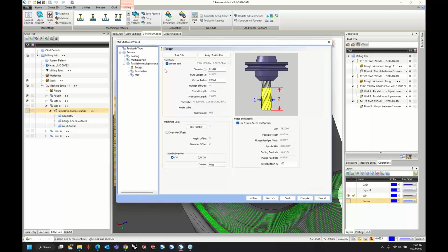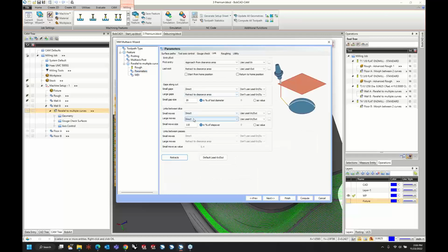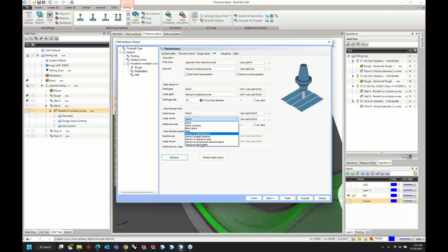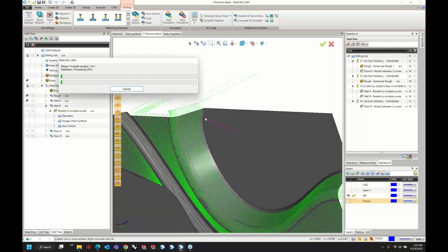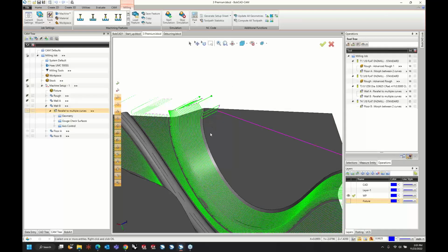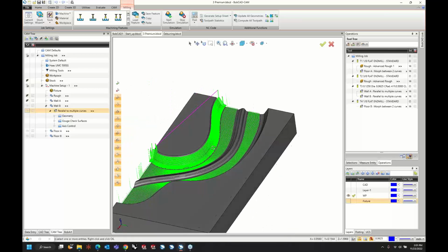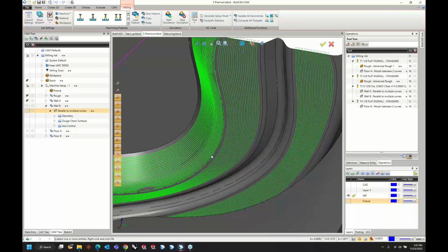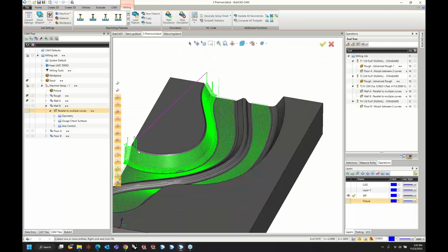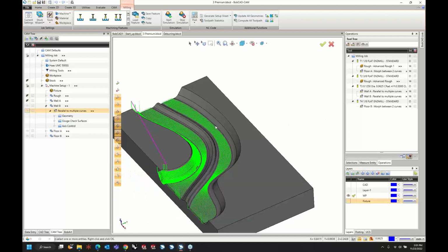So in this particular case, the setting that I used on the first wall was fine. I could change this large move to direct. I need to now change that to either feed or rapid distance. Let's change our retract back to user defined to 1.5. So that's a situation where the gap was too big in that cut. And that probably just changed because I told it to do exact surface edges, because that section's a little wider. So that's probably why it did that. But that's not the end of the world.